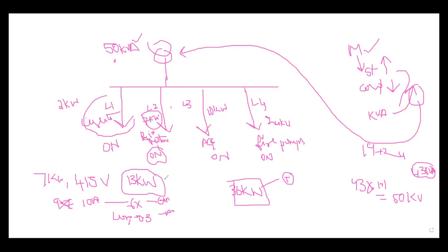6 times, right? So it won't be nearly 13K, it would be more than this. It comes to nearly 43 kilowatts or something. Let's see the calculation, because here the starting current power factor I am giving is 0.3, which is sine. If I convert to cos, everything would change. So it results in 43 kVA. So 43 kVA is the load I require, suppose, for the time being. But my present load is 7 kilowatt, and it is asking 43 kilowatt from the transformer.